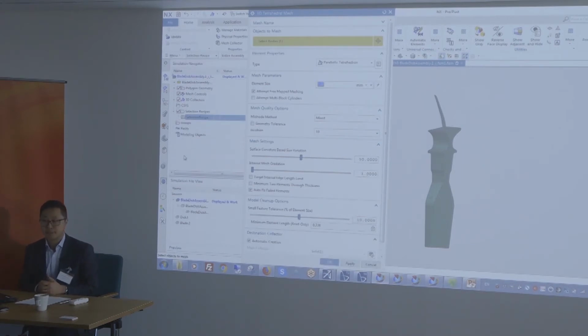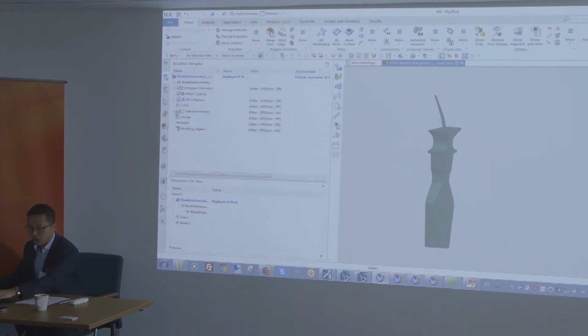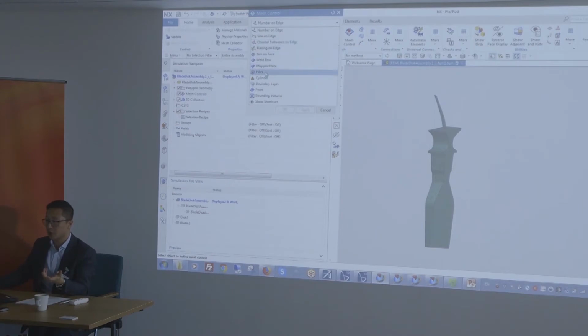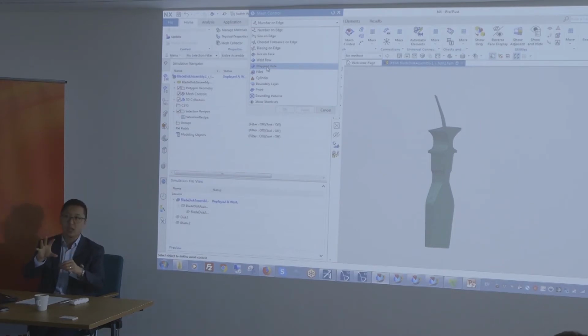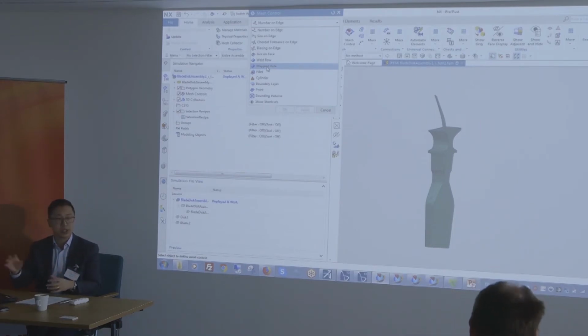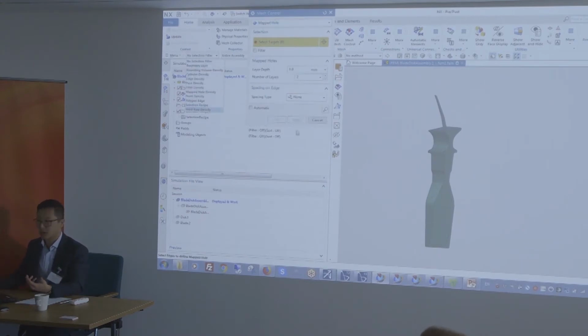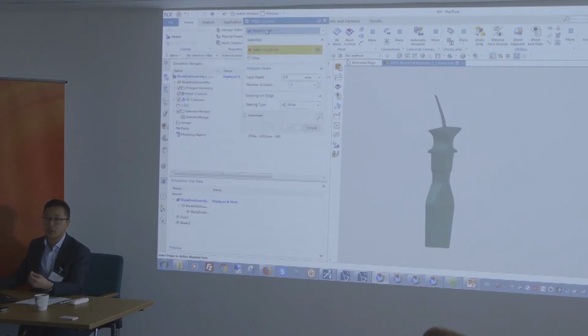Okay. Same thing for mesh controls. Let's say you do have a part with multiple holes, and typically around holes what you'll want to do is something like this, so a mapped hole. So you'll want a certain number of layers of elements around that hole to make sure that your bolted connection, you don't have any discontinuities. But these guys can also point to selection recipes. They're like this. So the mapped hole by default will automatically look for all circular features.